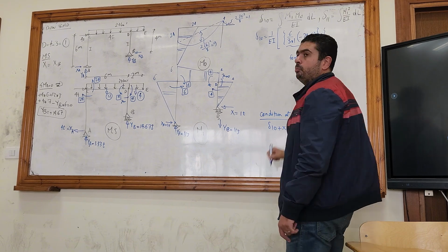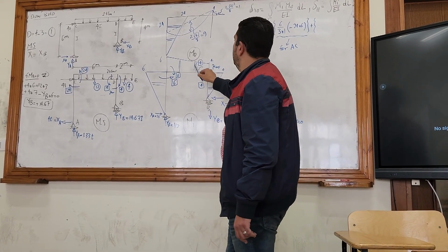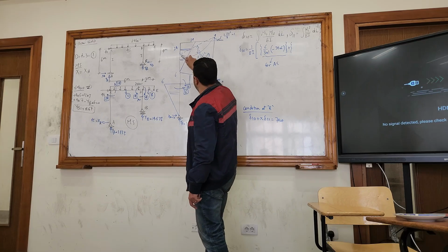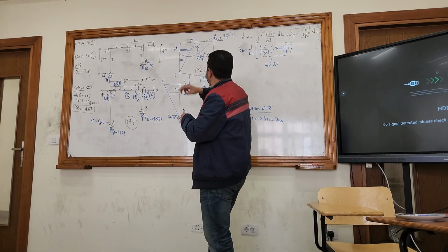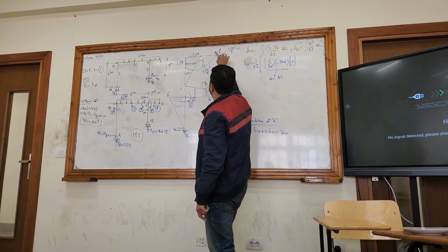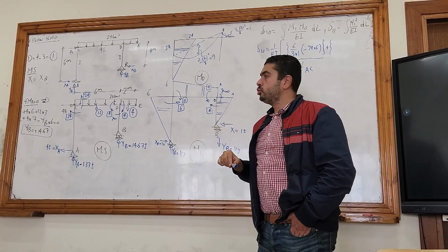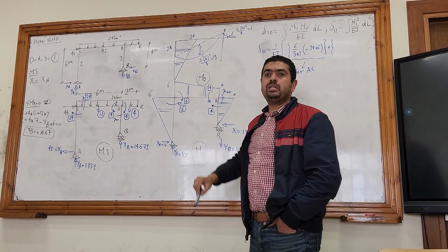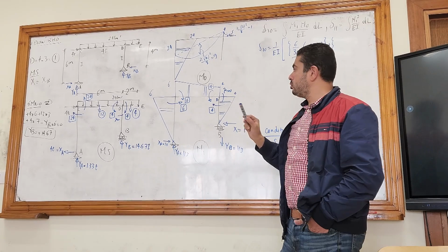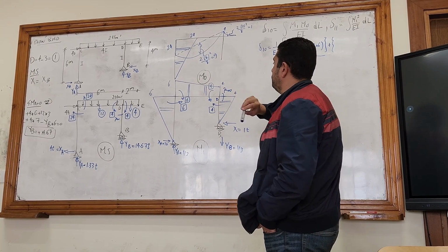You are going for another member, so plus. And please open a new bracket for the new member. I have here a trapezium with a trapezium several times. I told you that this is also called a trapezium with an inverted value. Okay? A trapezium and then a subtracted parabola. So I have here a trapezium with a trapezium, linear with linear, and then the trapezium with a parabola, so a linear with a curve. So let's start with the linear with the linear, the trapezium with the trapezium.